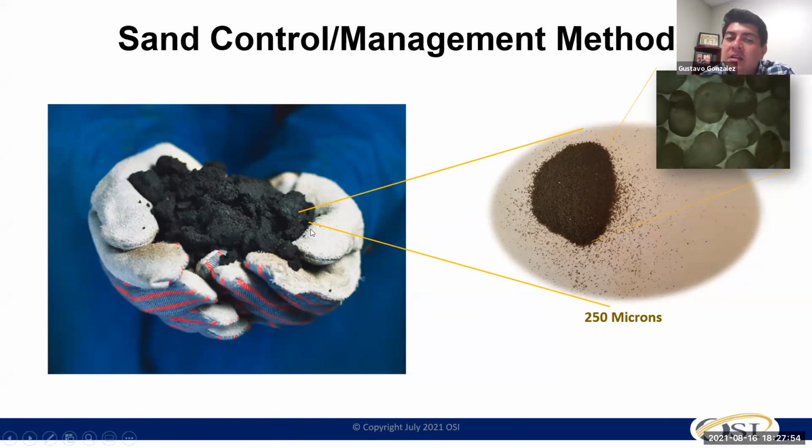It's a huge amount of sand, paste, or batches going through my pump, and that's what is going to cause the plugging effect, or stick my plunger. So I need to understand what I can do to start breaking or regulating this amount of sand before it goes through my pump.